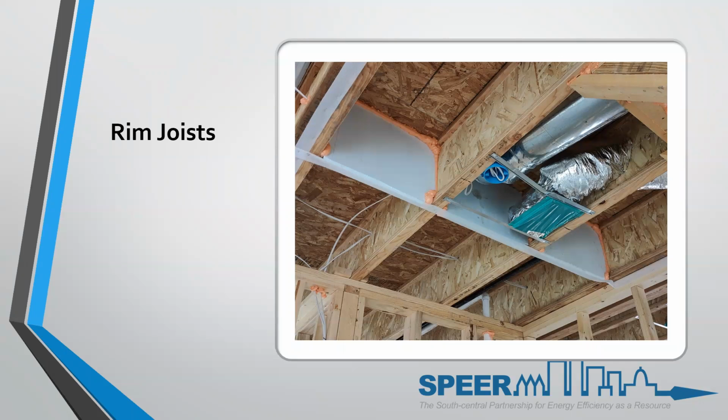Any air barrier will do, and this is meeting the intent. It's an air barrier installed directly below the second floor wall that is separating conditioned from unconditioned attic. So if I was to drill a hole off to the left, I do believe that was attic space, and the one to the right was conditioned floor. So they're making sure that they're splitting that by building a band joist in that lower section.